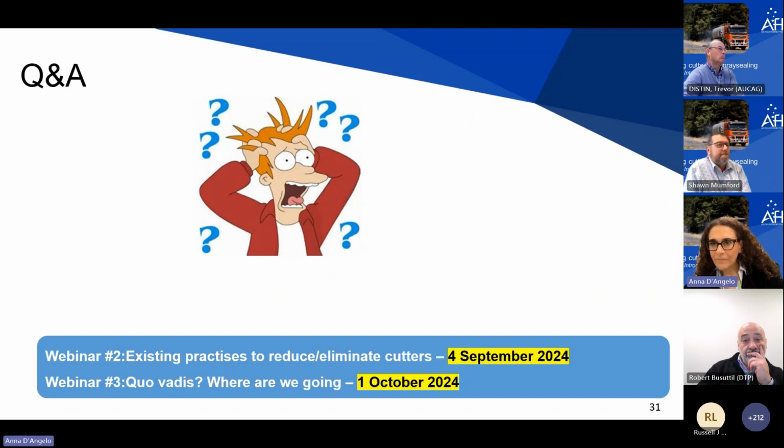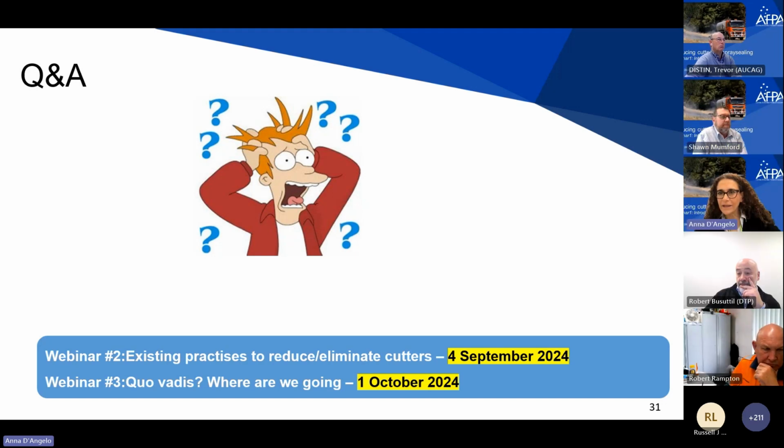Okay. And the question, what's the recommendation? What is the recommendation for flushing the spray equipment in between spray runs? So I can comment that my teams are using high flash cutters in their flush boxes, and that's what they're using. They're using the same product that they would be using if they needed to add cutter into their loads, basically. And I don't know if that's exactly a recommendation, but that's what we're doing, and it works okay.